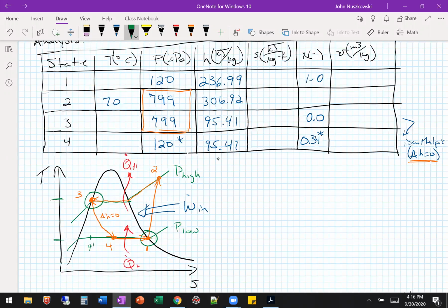Think of a very simple one shown in the slides. Let's say you have a pipe like this, but then you put it into a teeny tiny pipe, like the size of a needle you get your flu shot with, right? Think how much you have to push a plunger to get that flow rate. You're dropping that pressure because it's restricting the flow so much.